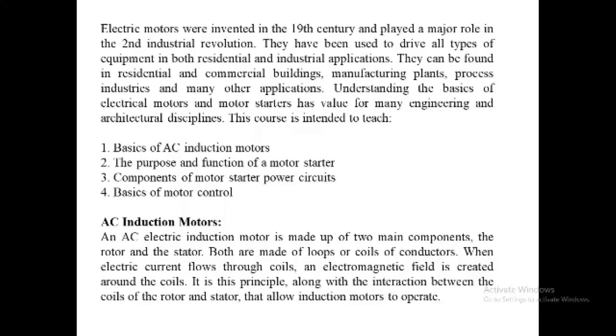When AC current flows in the stator, it creates a rotating electromagnetic field that produces a rotating force, that is torque, on the rotor. This rotating force causes the motor shaft to rotate, and the speed of the motor depends on the construction, the number of stator coils described as poles, and the frequency of the power supply.